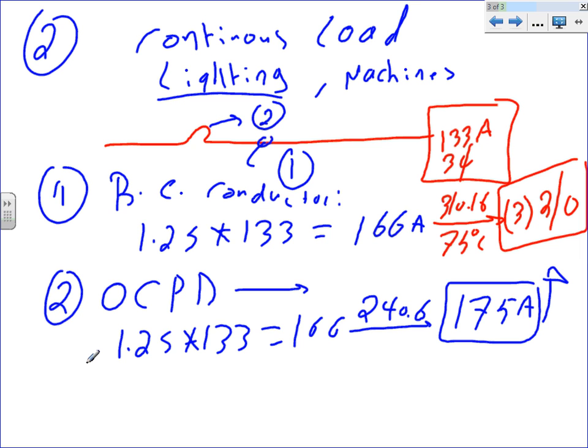From a reliability point of view, if you have a 100 amp load in your building, that must be a big important load, wouldn't you think so? 100 amp at 208, 3 phase, that's an important load. If you have 2 of them in one cable, guys, and one of them shorts, most likely the other will go with it. So from a reliability, maintenance, and troubleshooting point of view, it's a good idea to separate. That's CSK, not code or anything else.